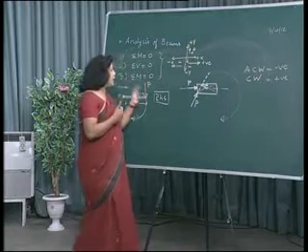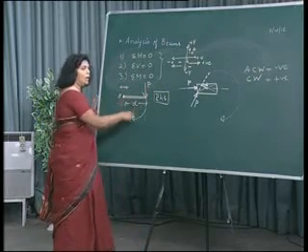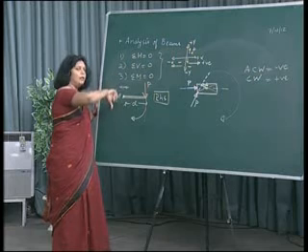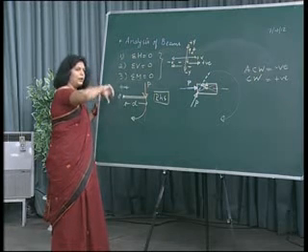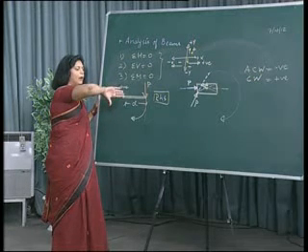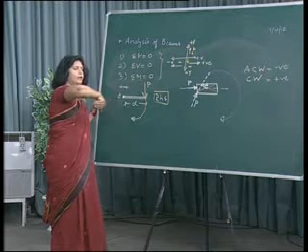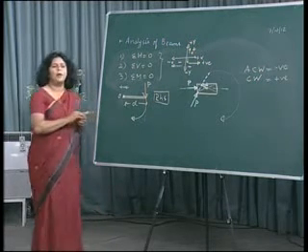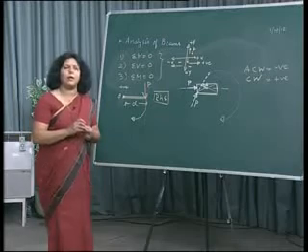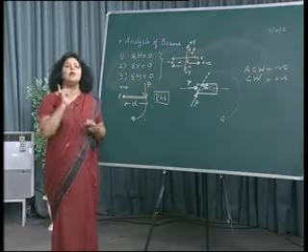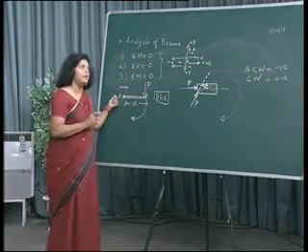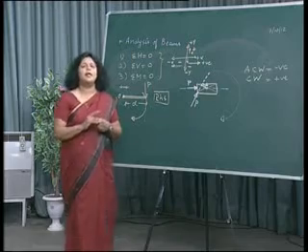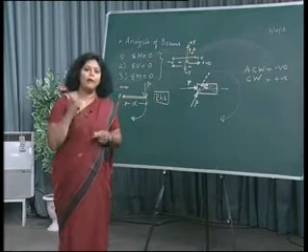In this particular case, the force is in the downward direction, so the right hand thumb will be in the downward direction, and all my fingers are showing the clockwise direction. So, that particular moment will be a clockwise moment. Always, whenever we are calculating a moment, the direction of the moment is considered with the help of the right hand.